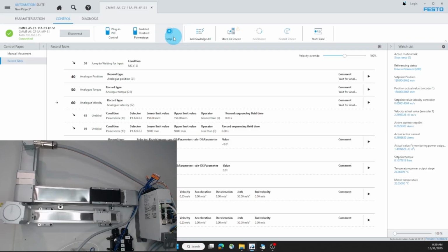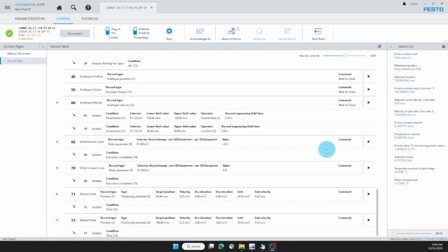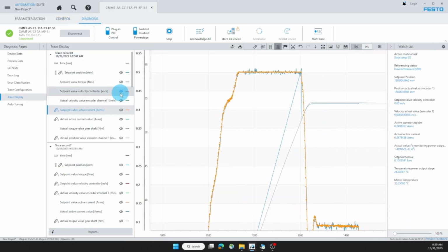These user-defined limits can be used to intentionally decrease either the velocity, torque, or current to protect the equipment that you're running with, or you may have to increase these values depending on the behavior of the system. And we can typically figure out which parameter needs to be changed based on the type of error, and then using our trace tool to figure out the behavior of the system. We can monitor the position if we're getting a position following error. We can monitor our acceleration if we're getting an acceleration following error, and we can compare that to these 3 basic user-defined limits to determine which one is the culprit.